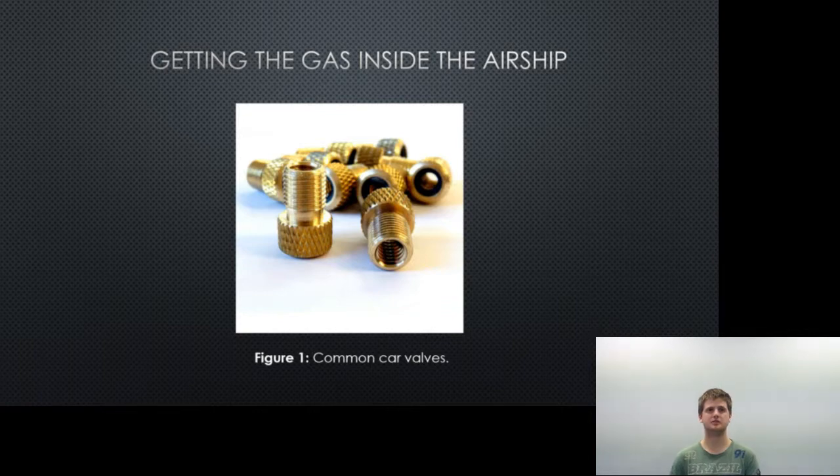The project also needed to regard a number of standards to avoid any unforeseen conflicts with stakeholders. Since the model will be operating in the air, the Australian Civil Aviation Safety Authority standards had to be considered. According to their standard AC 101-3, the airship should not exceed a height of 400 feet within 3 miles of the aerodrome unless permission has been granted by the appropriate air traffic control service or CASA officials themselves. Other standards that need to be considered are the Australian Design Standards for Technical Drawings. This will allow any confusion between the model specifics and the design drawings to be eliminated.